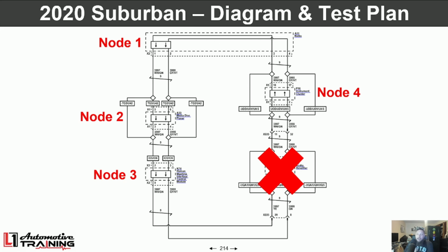So we're not too terribly far right now into the actual diag, but we do have quite a bit of information. We know what it's not immediately. We also know that only the radio talks and the CD player isn't. So because it's multiple nodes that are all down, I doubt it's a power ground issue. It's more likely that it's a physical network layer issue.